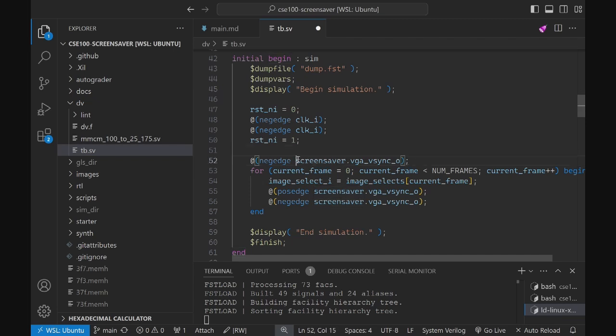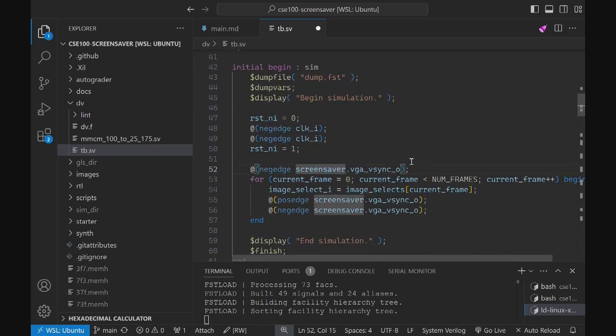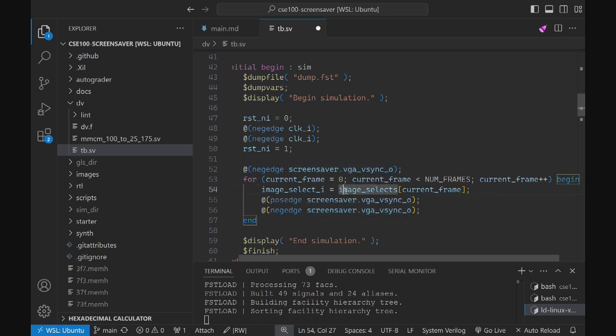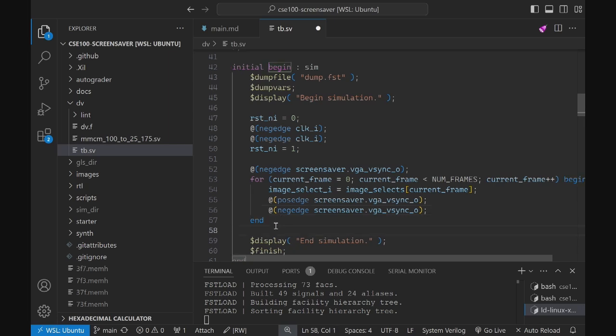So okay, good. We can see here what is happening is, we wait for the first vsync. And then after that, we request a different image from the screen. And then after that, we wait for another vsync. And it looks like we wait for vsyncs until we finally reach the correct number of frames. So if you did not implement vsync at all, let's say vsync was held high for the entire time, then what would end up happening right here?